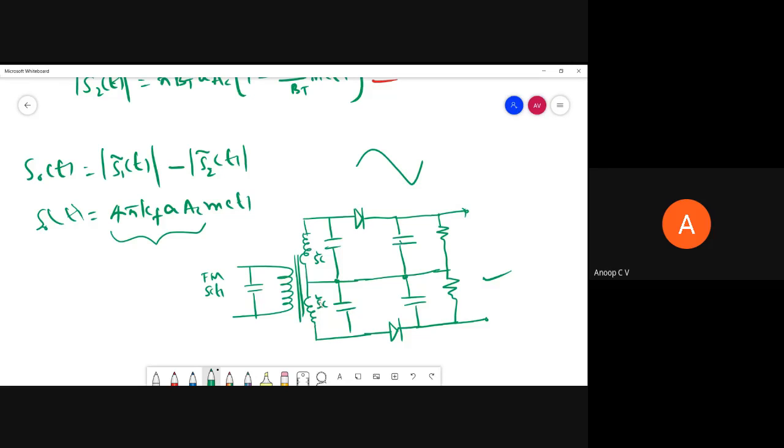We have a slope circuit given by an LC tank circuit. It's obvious that an LC tank circuit's impedance, or the gain it provides to any input, changes according to frequency. Whenever the frequency changes, the output amplitude also changes. So this LC tank circuit acts as a slope circuit, and we have an envelope detector following it.